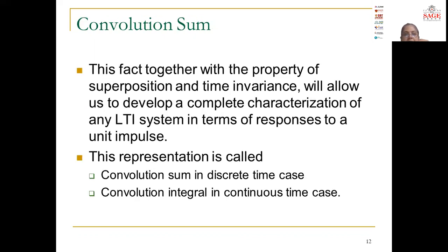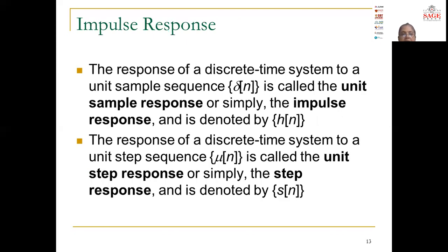Now when we talk about the impulse response, the most important property arises, which is known as convolution. This is a fact which, together with the properties of superposition and time invariance, allows us to develop a complete characterization of an LTI system in terms of its response to a unit impulse. This is also called the convolution sum in discrete time cases, whereas convolution integral in continuous time cases.